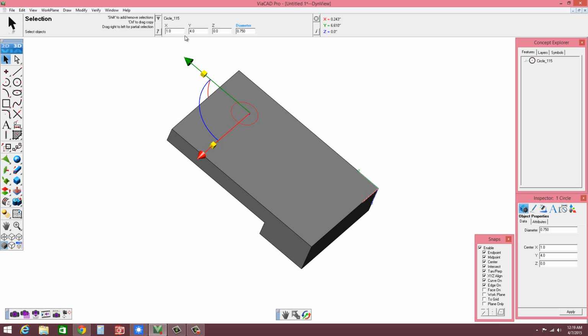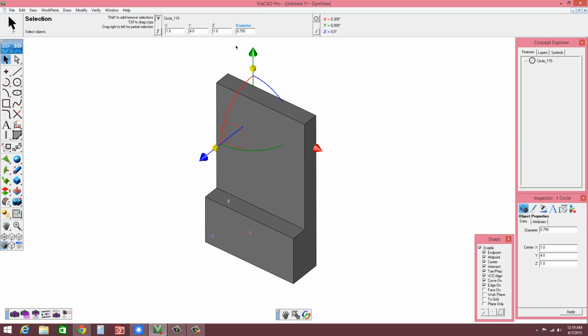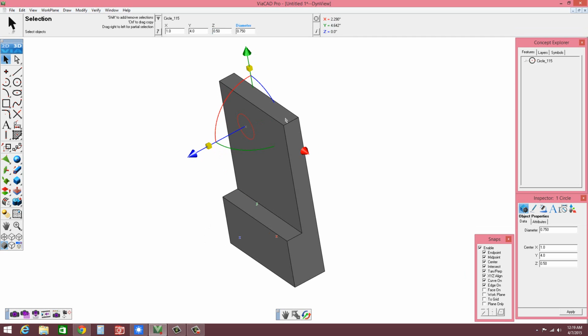Now if we wanted to, we could actually put it in the Z direction and put it on the front. In this case, we go ahead and type in negative 0.5. Oh, actually, I'm sorry, not negative in this case. I'm looking the other direction. It would just be 0.5. Or in this case, I could type in 1 because I'm already at half an inch. And that would place or position it. Unfortunately, it was under the absolute versus incremental. So we'll go ahead and set that to 0.5 again. And there. Now it should be on the front surface that we were working on.